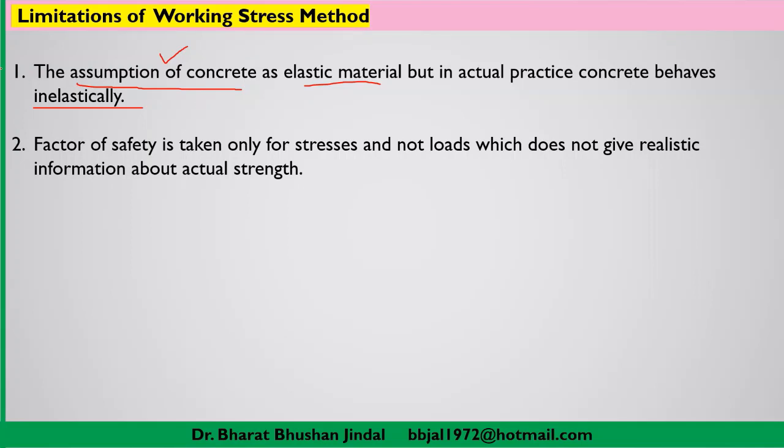Now the second important limitation is that the factor of safety is taken only for stresses. That means we are not taking loads into consideration. Factor of safety is not taken for loads, it is only taken for stresses. That means it will not give real information about the actual strength.